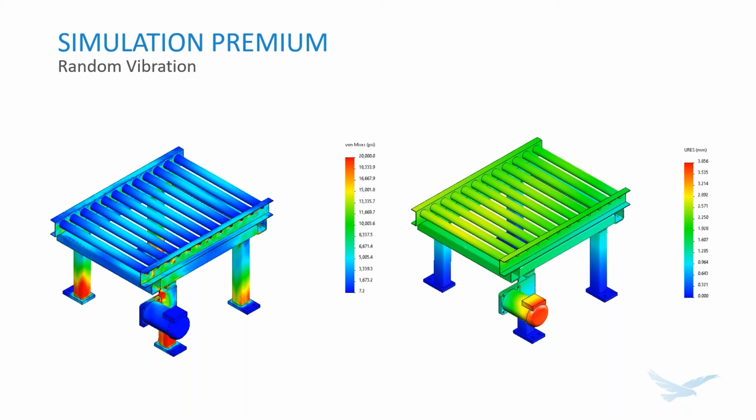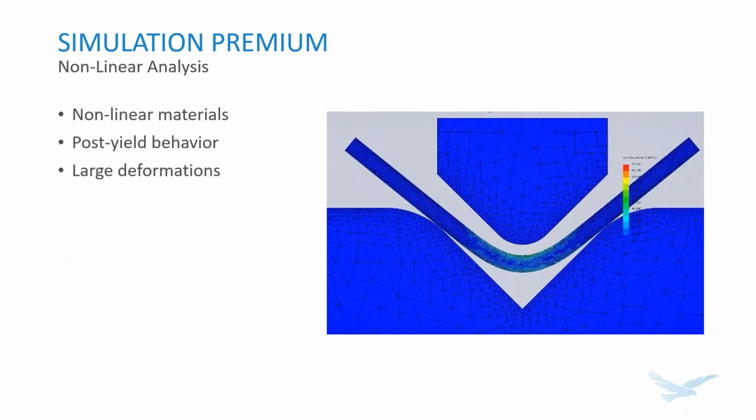So that about concludes our analysis of this scenario, but there are a couple other very capable tools I'd like to discuss in SOLIDWORKS Simulation Premium as well. Namely, one of them is nonlinear analysis. Nonlinear analysis allows you to analyze nonlinear materials, materials that don't really fit into FEA, that don't abide by linear static isotropic behavior and assumptions. So think rubbers, elastomers, those types of materials.